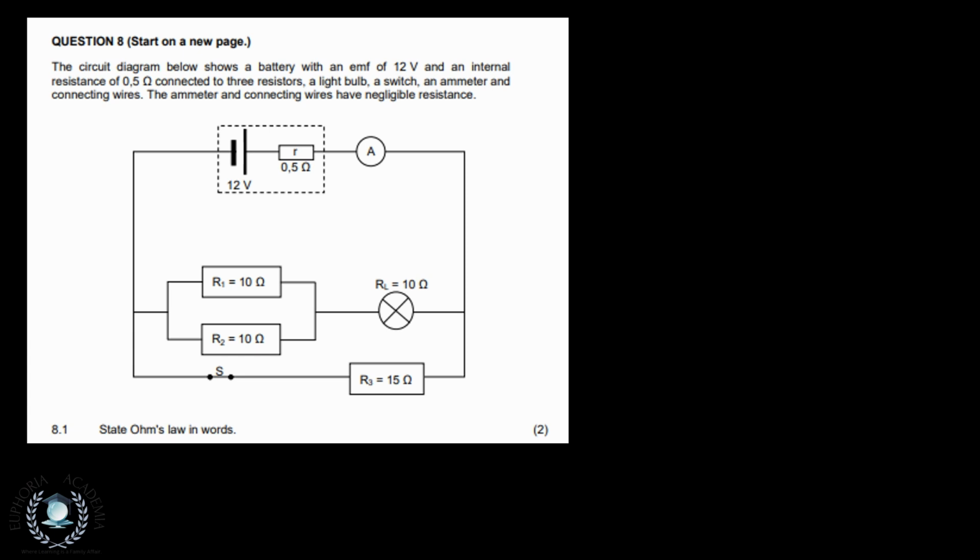Okay, let's quickly check out what's exactly happening in this circuit. Following conventional flow, the current will flow from the positive terminal of the battery. Maybe let's call that I1. Because we have a parallel circuit, this I1 will actually be the total current flowing throughout this circuit. So I1 will flow through this ammeter, flow down here, and then it will split into these two branches. That current will split. So maybe let us not call that I1 but I total.